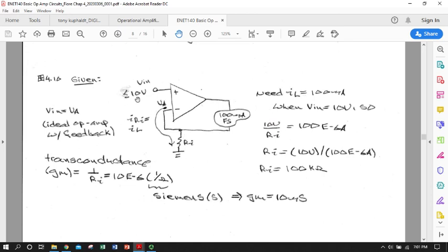And in this case, you can really see the transducer characteristic of this device. We don't care what V out is here. We need a current for a particular application. So we are definitely going from voltage to current. So we need the transconductance, the 1 over Ri, that will give us that. So we basically go back to the formula we derived. We need the transconductance 1 over Ri being in the right range.